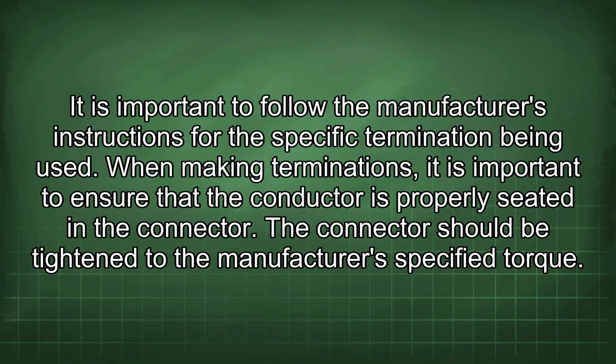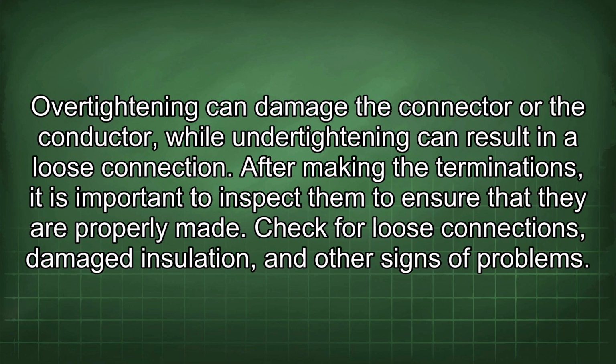When making terminations, it is important to ensure that the conductor is properly seated in the connector. The connector should be tightened to the manufacturer's specified torque. Over-tightening can damage the connector or the conductor, while under-tightening can result in a loose connection.